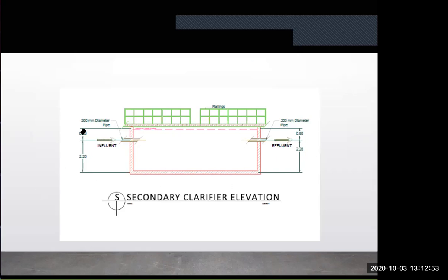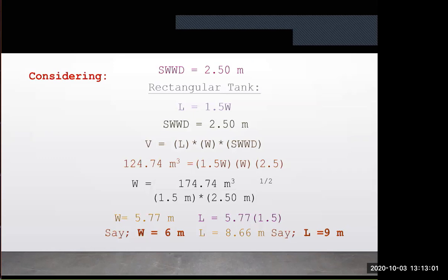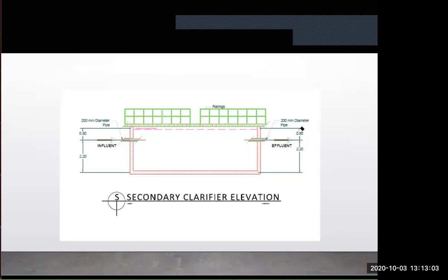So this is now your inlet. That is now your pipe. Okay. And then we said 2.5 earlier, right? But you can adjust that one. You can make it 2.2 and then your freeboard equal to 0.8. Because you need to position your pipe such that there is still water that will now pass through your pipe.